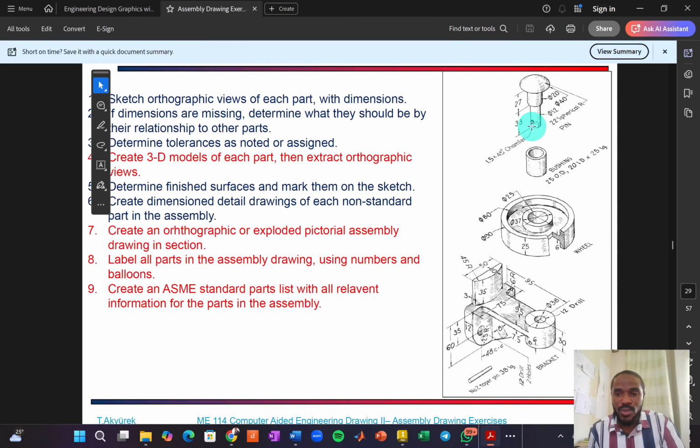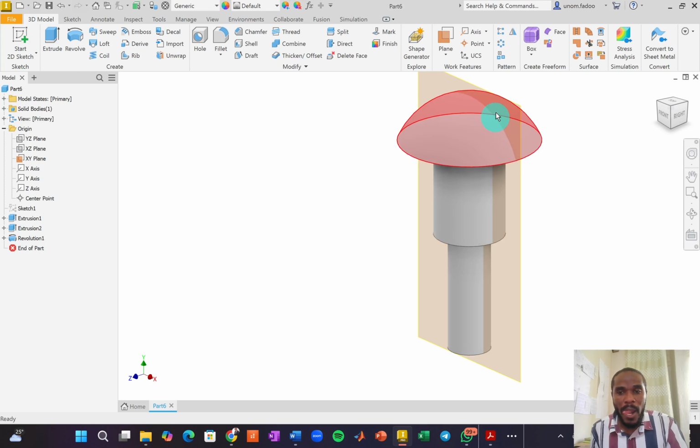So what I want to do now is to come back here and create two different planes, symmetrical about this center plane, that will be where the taper pin starts and where the taper pin ends. Remember, the full length of the taper pin is 38 millimeters, right? So if this XY plane is bang on in the middle of the pin, then we need another plane to its left by a distance of 19 millimeters, because if you divide 38 by 2, you have 19, and another one to the other side by 19.